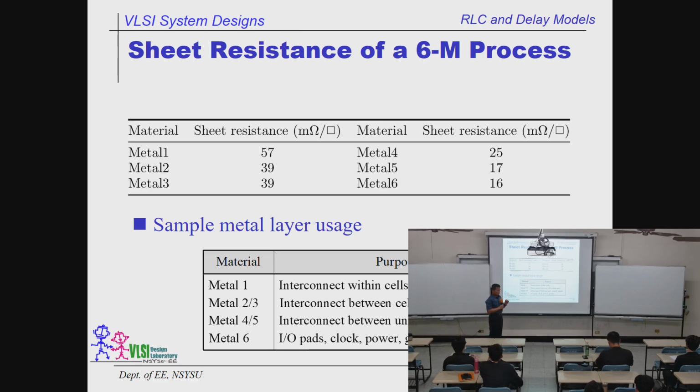If you don't reset your flip-flops at the initialization stage, the D flip-flop will be locked in the middle of nowhere. You get a big X. You don't have a 0, then a 1. You cannot assume the D flip-flop will give you a ground. That's impossible. You cannot assume that it will give you a high VDD. That's impossible. It will be trapped somewhere in the middle. So you have to reset it before you use it.